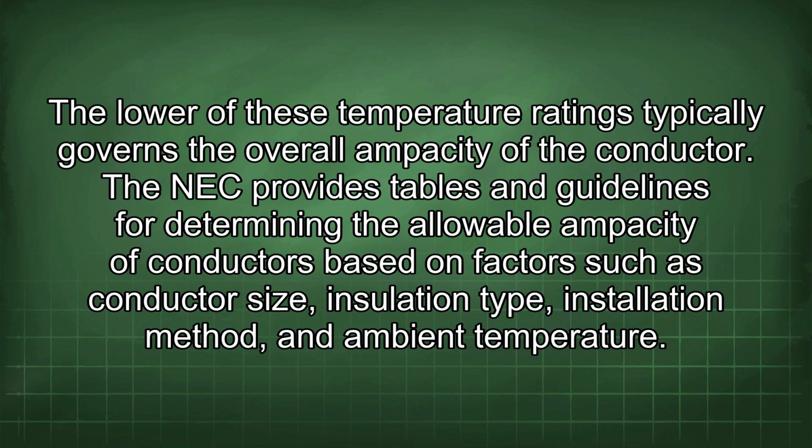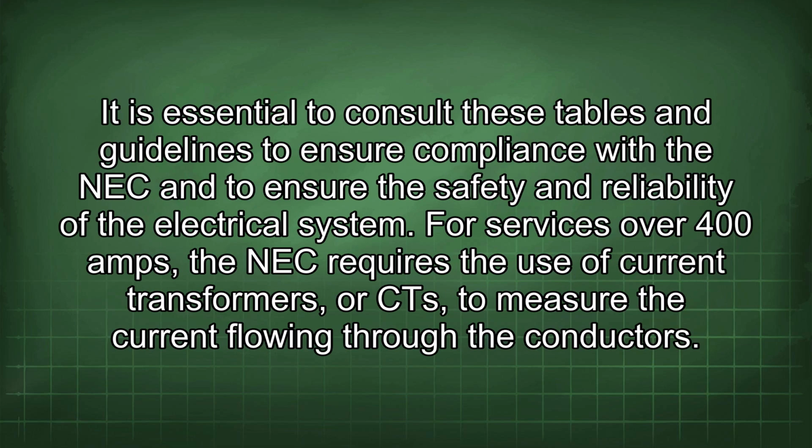The NEC provides tables and guidelines for determining the allowable ampacity of conductors based on factors such as conductor size, insulation type, installation method, and ambient temperature. It is essential to consult these tables and guidelines to ensure compliance with the NEC and to ensure the safety and reliability of the electrical system.